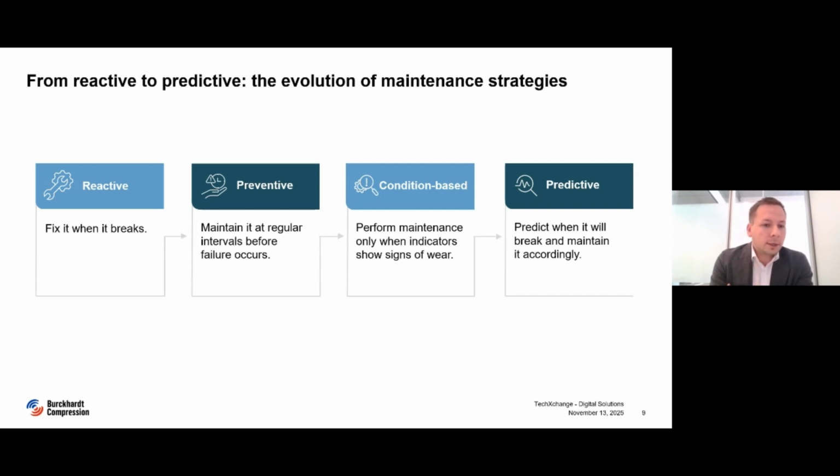As an overview of maintenance strategies, it usually starts with the least advanced one, the reactive. These strategies have been developed as assets in industry developed. So reactive is one where, of course, a failure is fixed only when a component breaks. And in theory, that can give you the highest lifetime of components. Such an approach has, of course, the downsides of unscheduled, unplanned outages that can lead to higher costs of maintenance and the need to fight consecutive damage of your compressor.